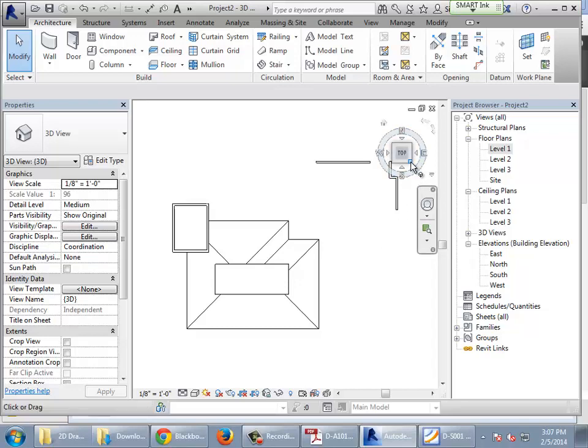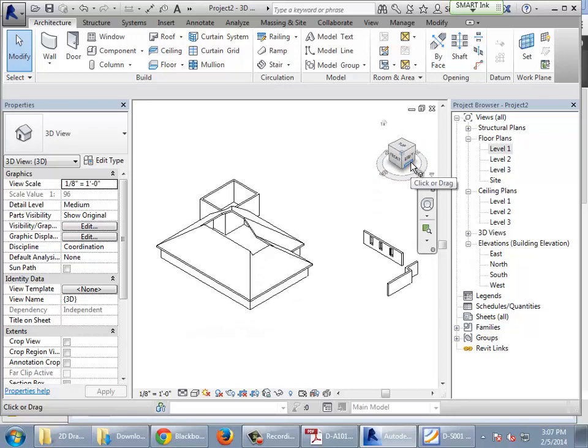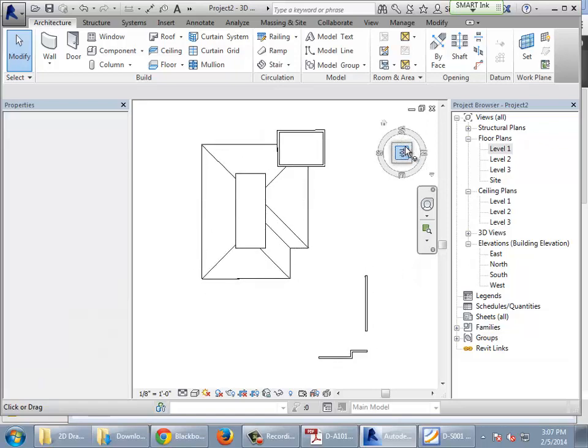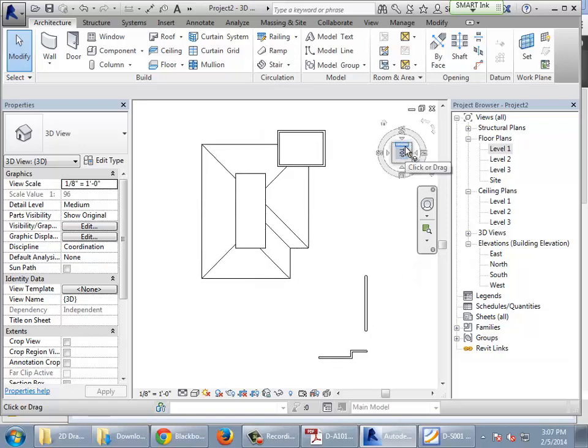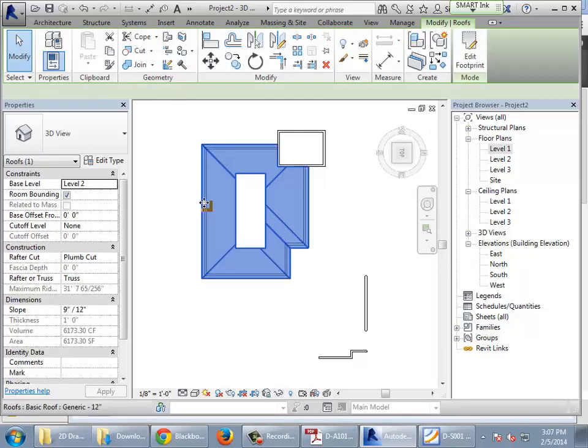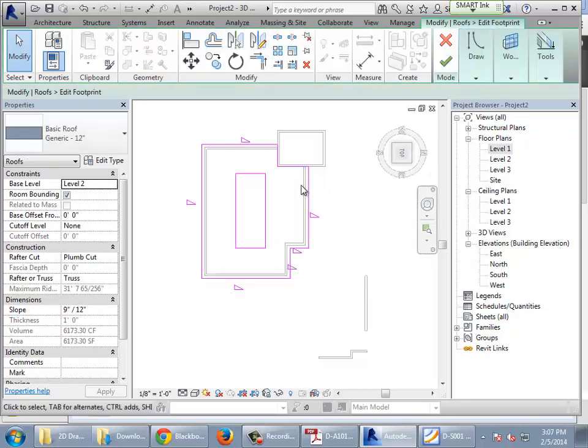But I'll give you one other trick that's going to help you out. The truth is, if that hole is relatively even, there's a really clean relationship. The hole is probably almost guaranteed to have the same distance from the edge on all sides. So how you can do that is, over here, we'll edit that footprint.